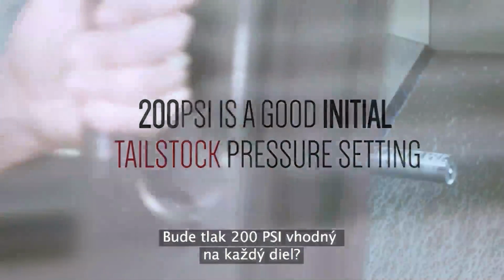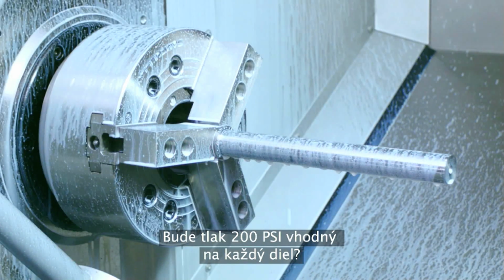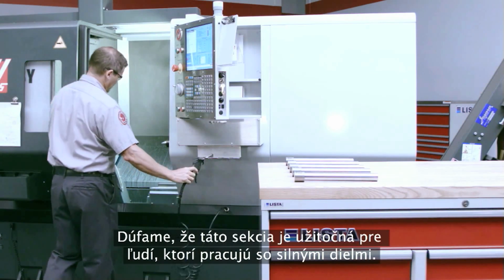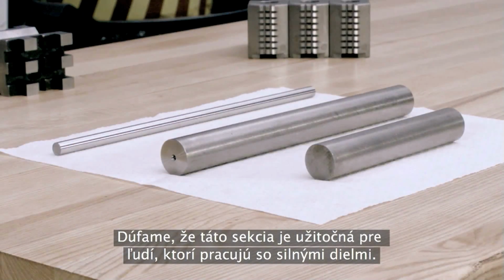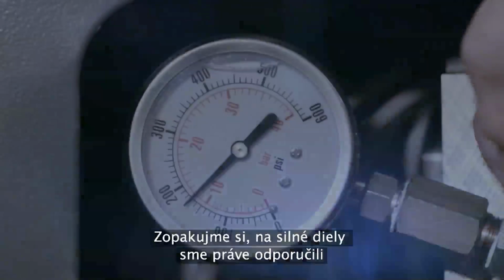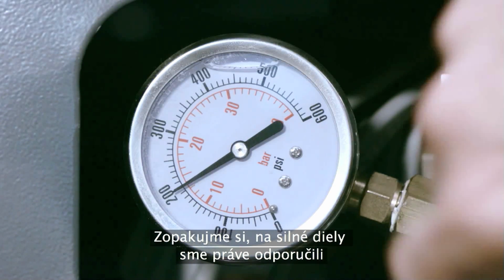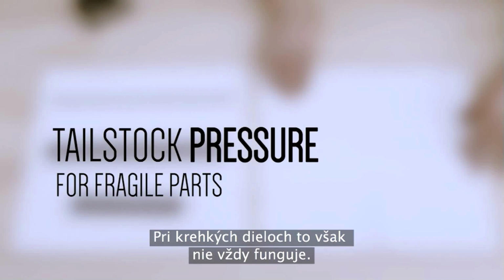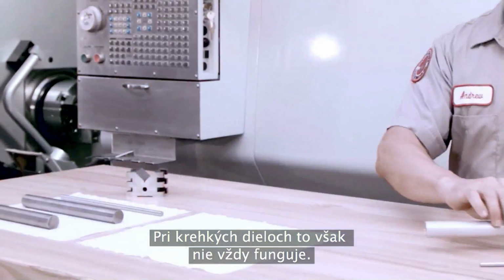Will 200 psi work for every part every time? Most likely not. But again, it's a good place to start. We hope this section is helpful for the folks who are working with stouter parts. But what about parts that deform easily? To recap, for stout parts, we just recommended a tailstock pressure of 200 psi as a good baseline. But with fragile parts, this doesn't always work.